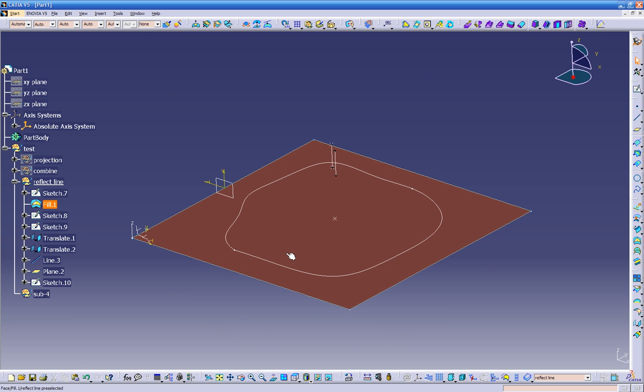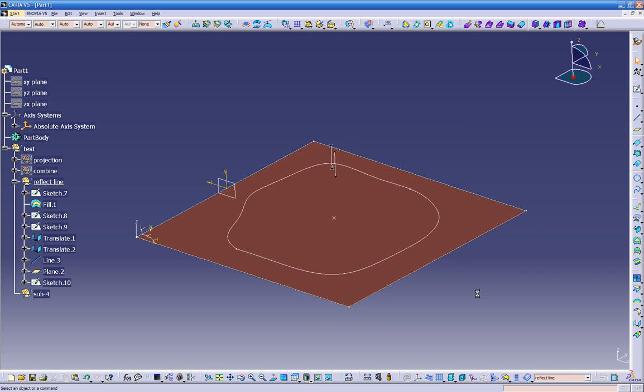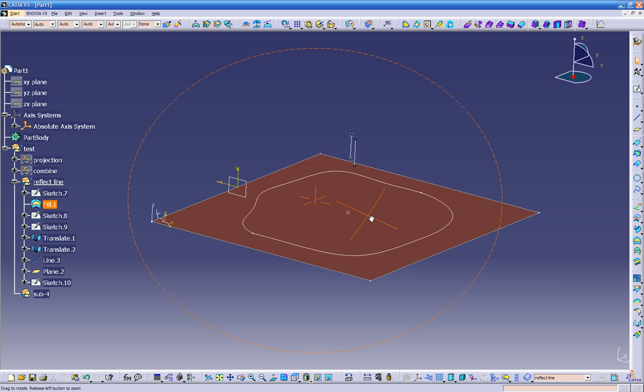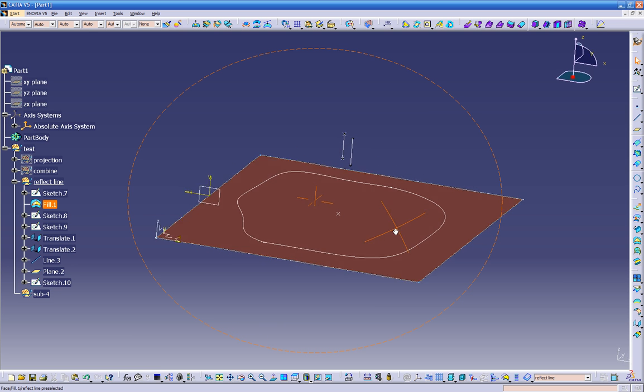But the reason I did some 3D construction geometry is just to get you used to it. You can create points in 3D view, you can create lines, axes, circles, splines. All these options we can create in a 3D view. We don't have as many options as in a sketcher. The moment you open a sketcher, you can tell how many options you have to create your geometry. But we don't have that many options and icons to create our geometry in a 3D view. So it's always better to use the sketcher to create your stuff. But when I do quick and dirty constructions, sometimes I use the 3D constructions. You'll get used to it, and when it comes to it, you'll choose whatever is easier.